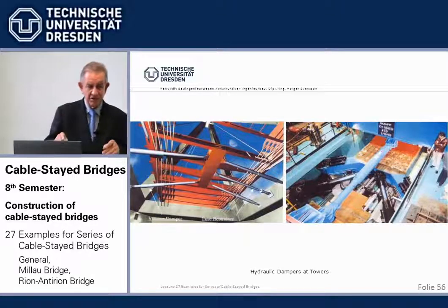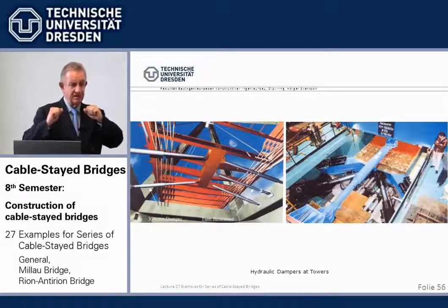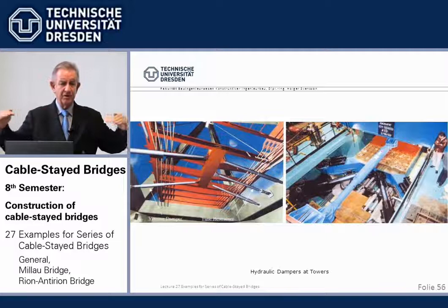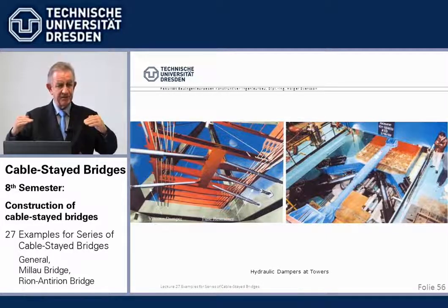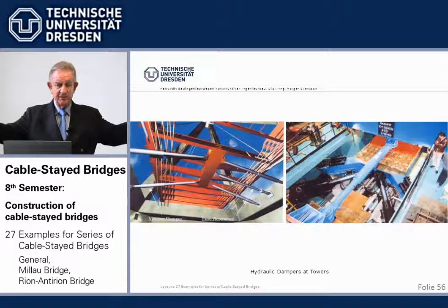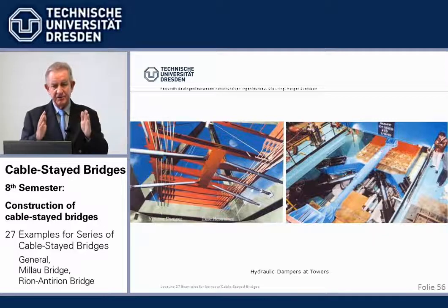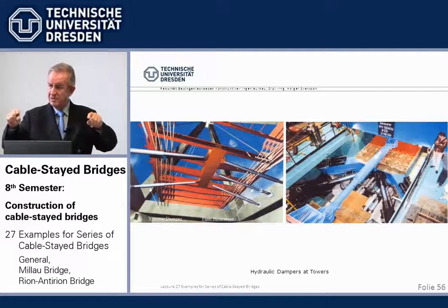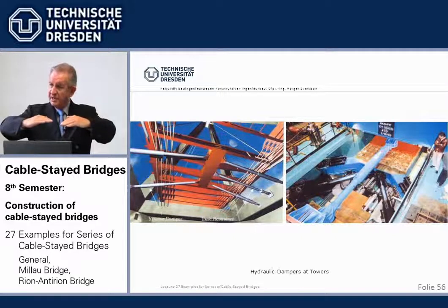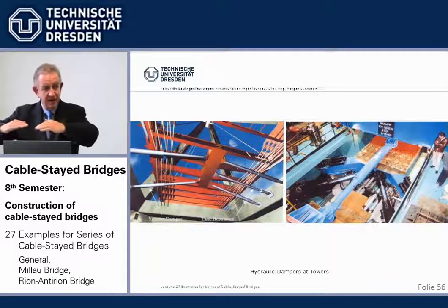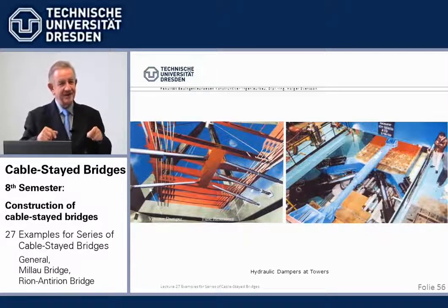Now, I've told you how we stabilize the tower head. How do we cater for the beam changes in length? We do that by having the beam, over the full length of something like 2.5 kilometers, hang freely in the cables. There is no longitudinal connection between the beam and the towers. It's just like a swing, and it can swing like a children's swing in a play yard.